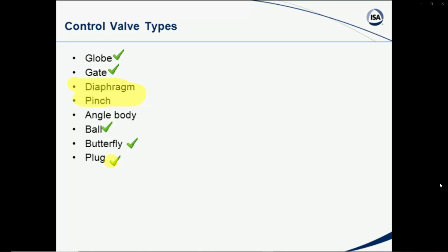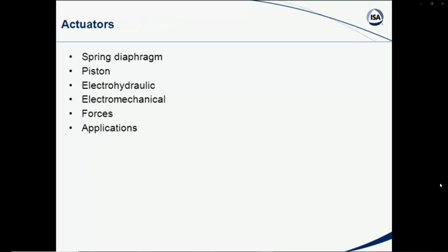And so these are different types of valve bodies, and then special cases you will see valves built with an angle body that are on occasion used as far as the control mechanism is concerned for a particular loop. But these are just some of the many types of control valve that you might run into and that you will need to know a little bit about on the particular exam, because they may ask you for application information.